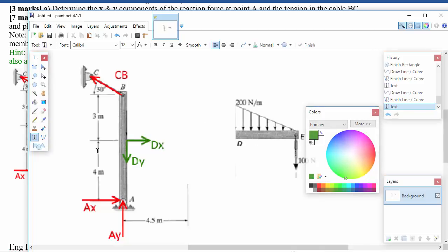And we are going to have a moment. So before we add the moment, let's look at how these are going to be repeated on the other side. So Newton's third law says the force that DE is placing on ADB in the y direction is equal and opposite to the force that ADB is placing on DE in the y direction. So that would be this right here. That's the same dy as this one, and same in the x direction.